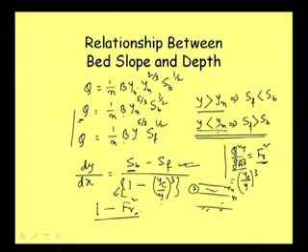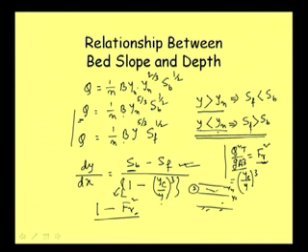From that point also we can see, if our depth of flow is less than y c, then it is supercritical flow. And when it is supercritical flow, Froude number will be greater than 1. So 1 minus something greater than 1, because if it is greater than 1 the square term will be further greater, will become negative. So, by applying those concepts also we can analyze the characteristic of gradually varied flow.